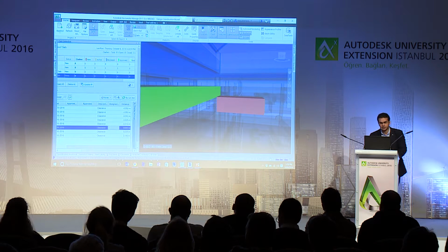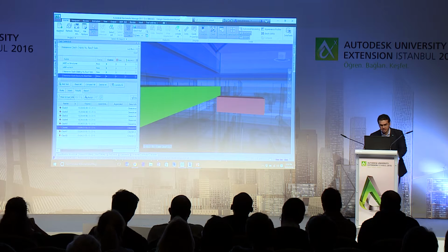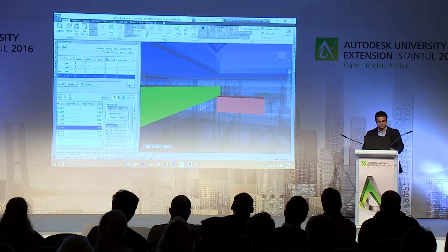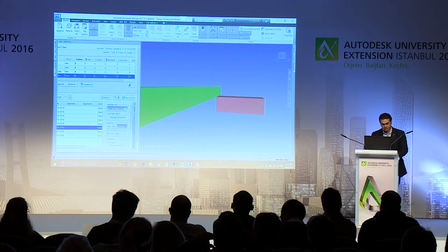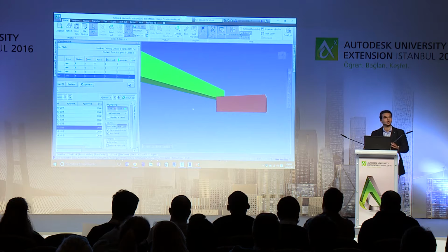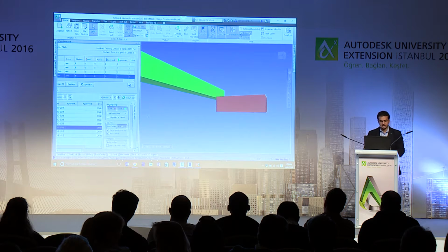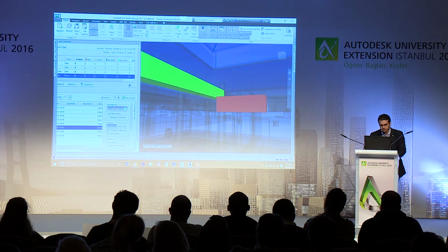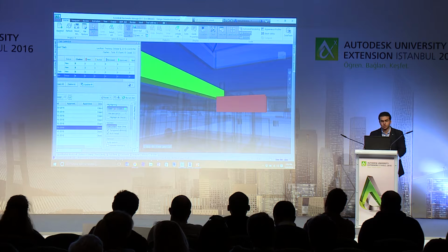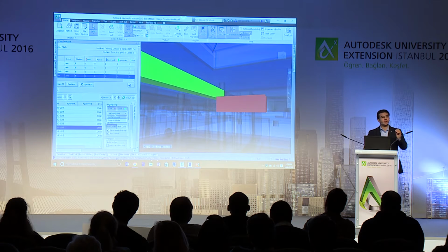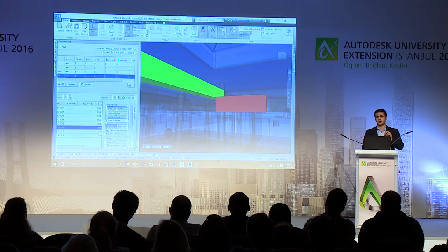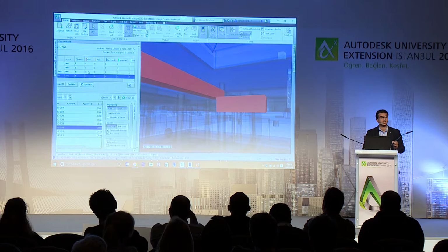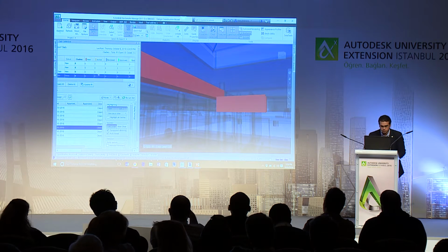The second thing that differentiates the way you can manage clashes in Navisworks is the ability to control the visibility. What it means, you can hide other elements to focus only on specific items. Of course, you can add markups. I'm not gonna go into deep details. You can dim others. You can choose auto reveal, and even you can do color coding. You can filter it by item 1 with one color and item 2 with a different color, or you can go by status. So according to the status of this clash, you will represent your clashes here.